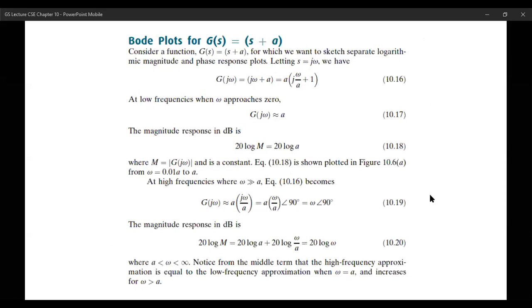Okay, so now let us start with the simplified transfer function. Say that we just have a zero at s equal to -1. So how are we going to approximate it using simple straight lines? Those straight lines are known as asymptotes. So instead of drawing a curvature, can we actually draw straight lines to plot the Bode diagram or not? This is what we are trying to do. So this simple zero is G(s) equal to s plus a.